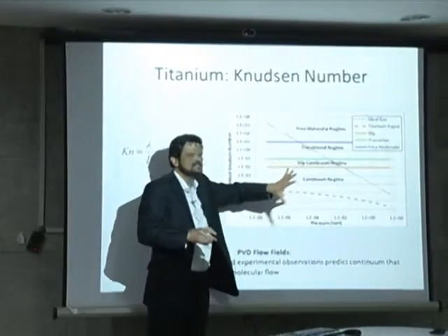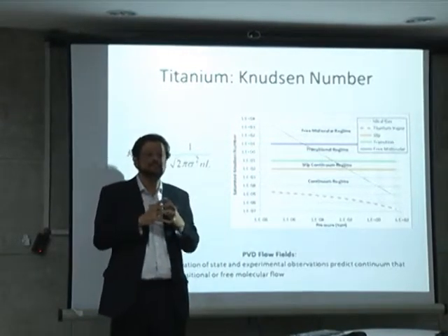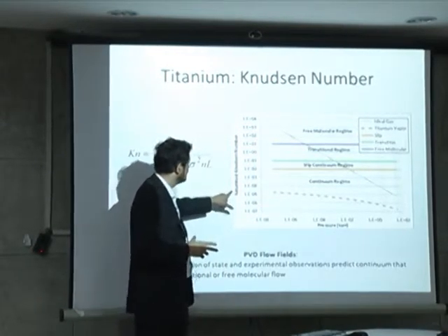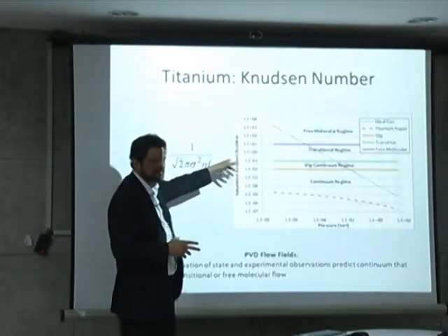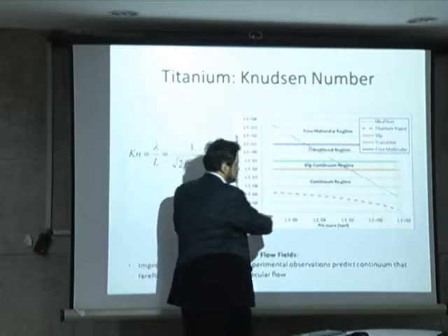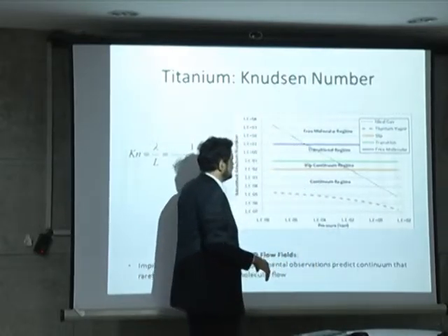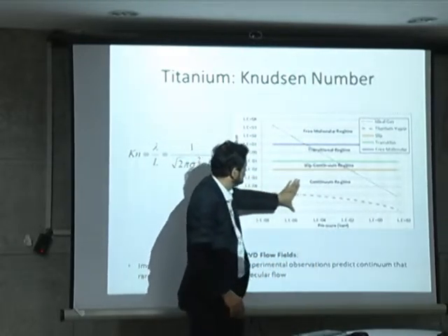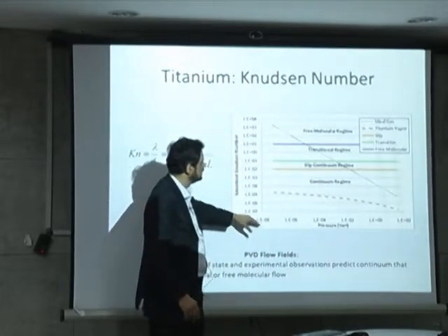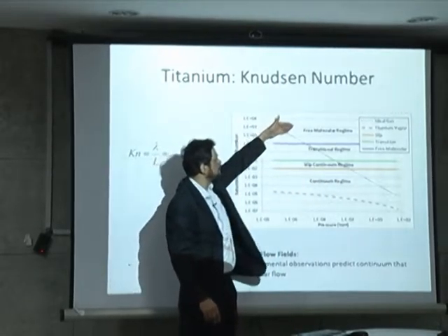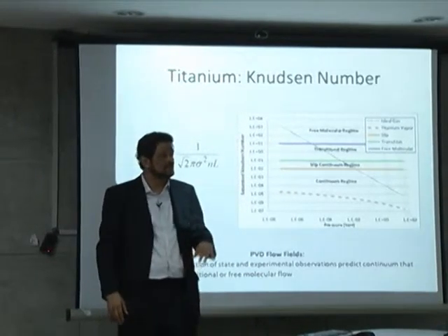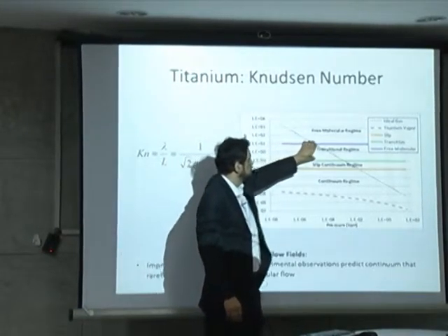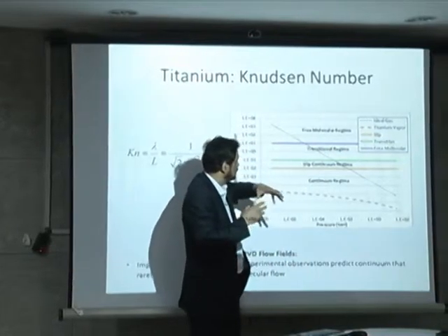This figure nicely summarizes the different regions that you're looking at. This is the Knudsen number, a saturated Knudsen number. They've defined it in a certain way. This is the pressure. What it is saying is that there is a continuum region when it is low Knudsen number, and then there is a free molecular region. That means the molecules just go freely, they don't even collide with each other. Before that, there is a transitional region where they collide quite a bit.